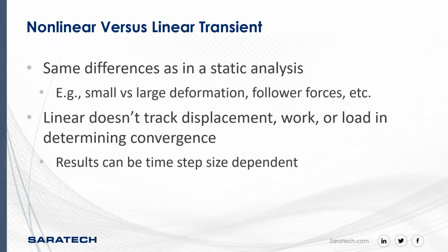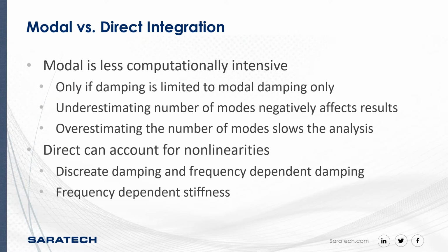Also, something to keep in mind is that a linear analysis doesn't track, it's not looking at displacement work or load convergence. So as it marches through time, your results can end up being time step size dependent. So that's just another thing that you'll have to be concerned about in a linear transient analysis. So next is the modal versus direct integration comparison.